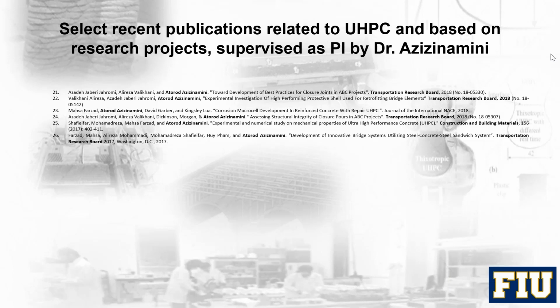Okay, and then do you have to get underneath the top mat of rebar? Do you have to remove anything, or just maybe the damaged area? Any thoughts? Yes, I was discussing this with our colleagues in Switzerland, and their opinion is that you don't even need to remove all the contaminated concrete. That was the point I was making, that you only need to go 1 inch beyond the reinforcement.